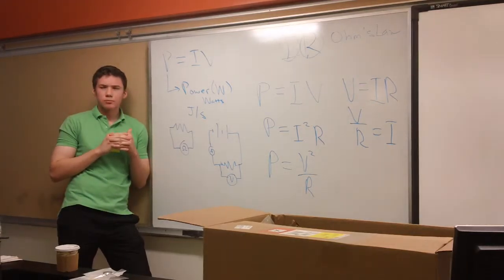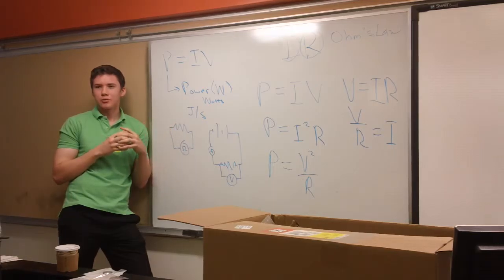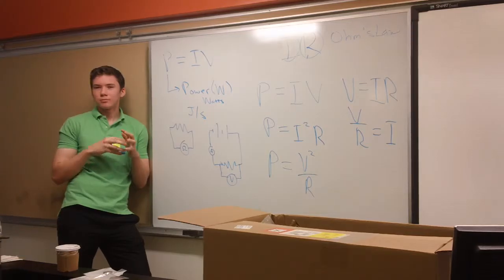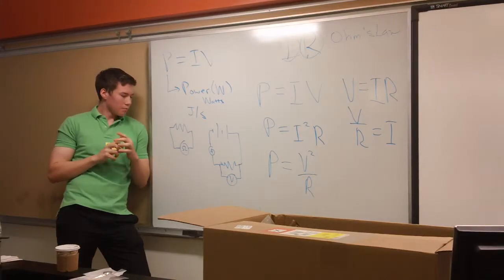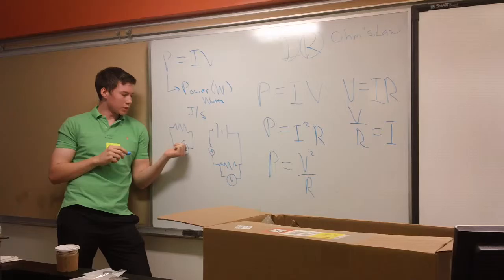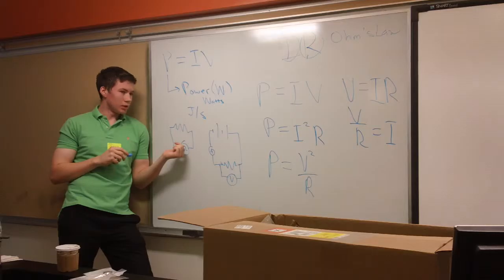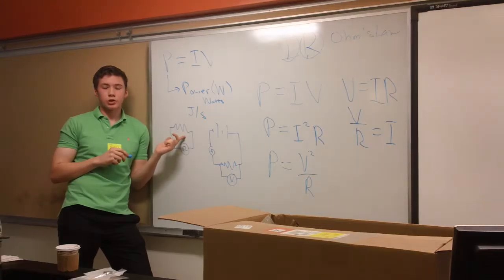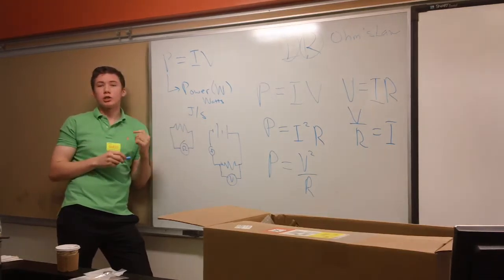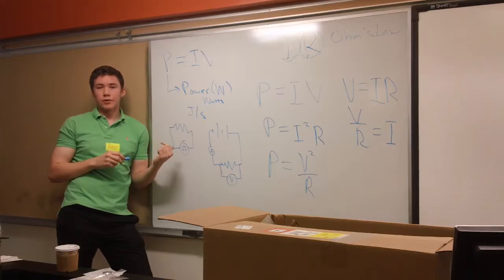Any other questions on this? I'd be amazed if everything sunk in after just this lecture, so you guys have got to have some questions. So that one isn't connected to a circuit? No. Because the way that it works in this configuration is that this is actually sending a small current across this, and then it measures the voltage across that. And using Ohm's law, it actually determines what the resistance of it is.